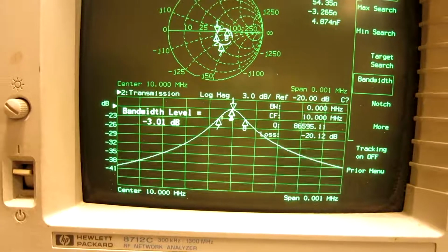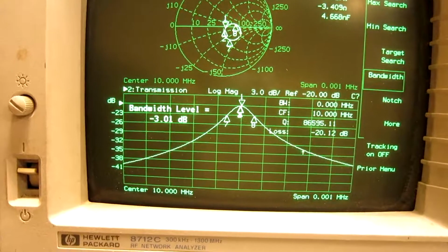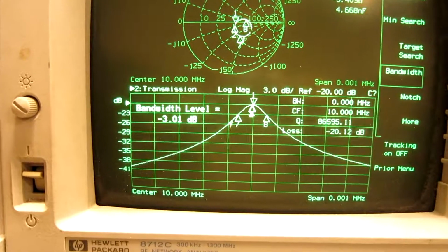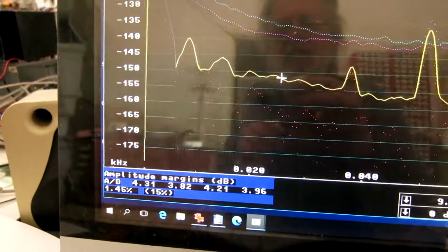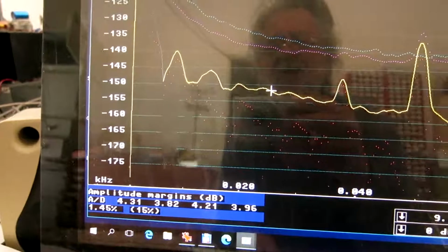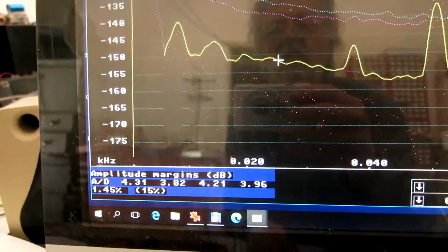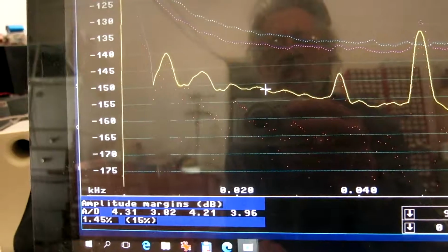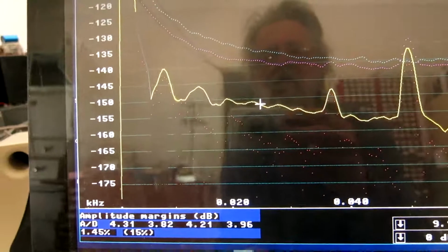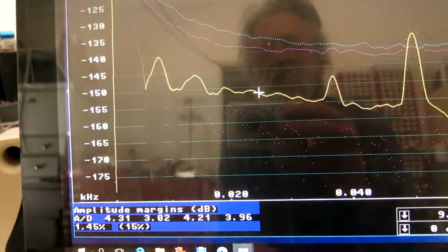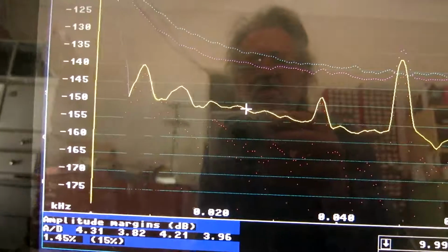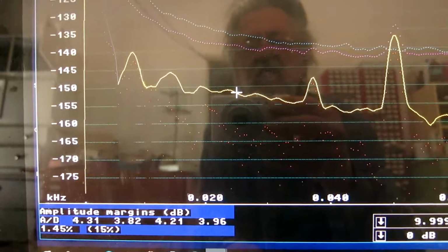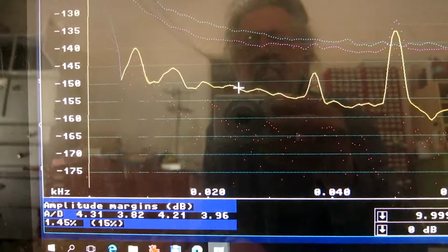Now I can measure the noise through this filter when using the Wenzel oscillator as a signal source. The filter attenuates by 20 decibels now. To compensate for that, I have increased the gain of the UADC4 and I have removed 2 decibels of attenuation that I was using before when measuring the Wenzel oscillator directly.